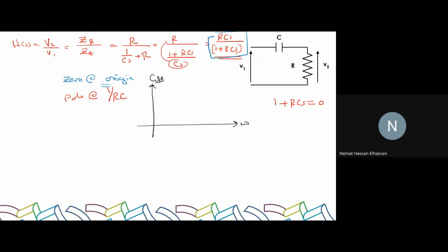Instead of saying that it will increase at the break frequency, I go and find point omega equals 1. And it will increase with a straight line from point omega equals 1. So this represents this 0 at the origin, with an increment of 20 decibels per decade. What does that mean? It means that when I go to point 10, this is 0.